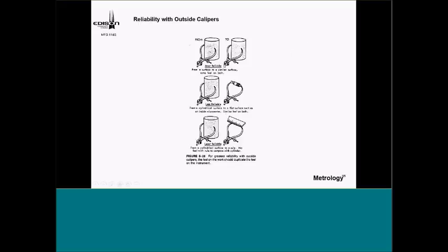Reliability, and again, if we're checking comparison, then it's most reliable. Less reliable is using a precision measuring instrument, like an inside micrometer. And again, the least reliable is using the scale. But if I give them a tolerance of plus or minus 1/64th of an inch, I would still want them to get used to it. There are times when you have to do this, especially in the industry.